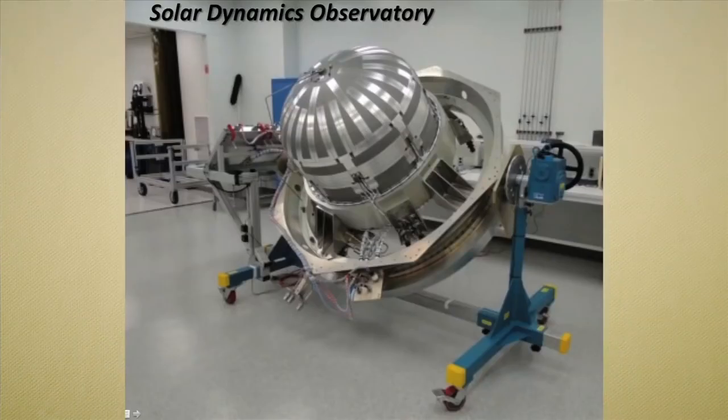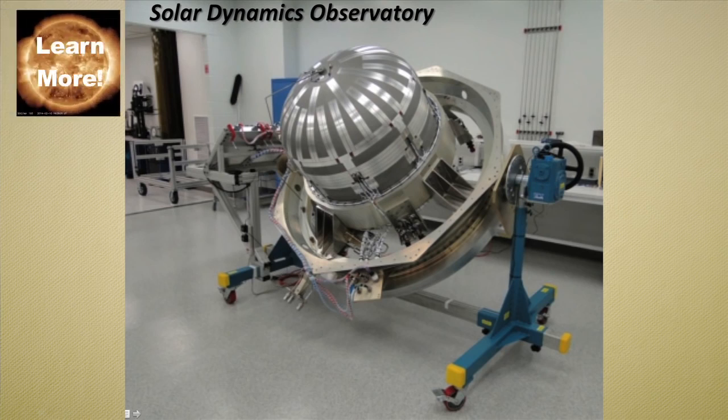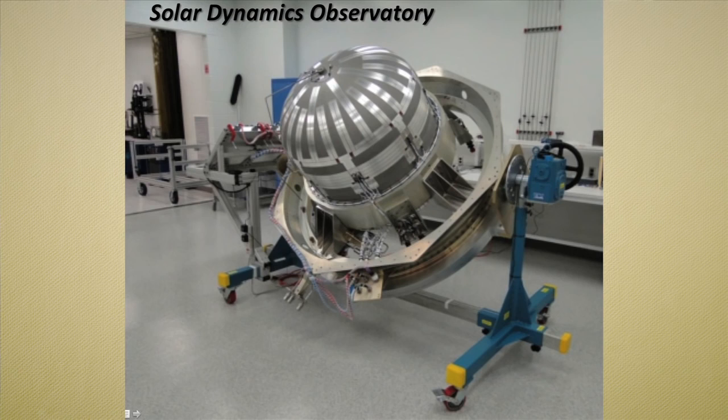And so in Phase C, you see a picture here of the fuel tank for one of our missions. This was from the Solar Dynamics Observatory, which is on orbit in geostationary orbit. And this is what's happening in Phase C. You finish your design, and now you're actually bringing the parts together, not the full spacecraft, but the parts of the spacecraft, and you're testing them at the component or subsystem or element level.